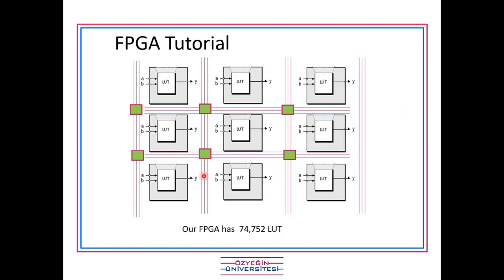There are interconnections here. We can see them here. Sometimes my design can be finished, right? It can be enough. I mean, only one LUT can be enough for it. So I can do it in only one logic block. If my design is small, it can be done in that. But sometimes I have bigger designs, a lot of inputs and a lot of outputs, and I have to use many of the LUTs to make the design. So that's why we need the interconnections.